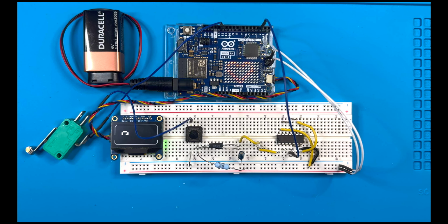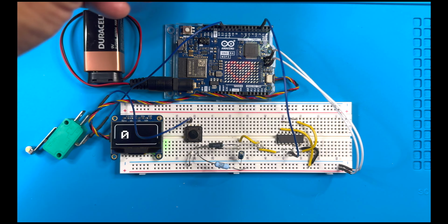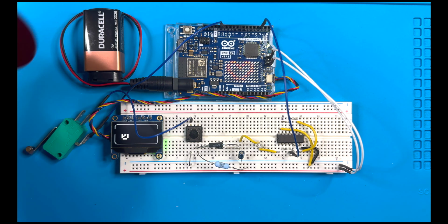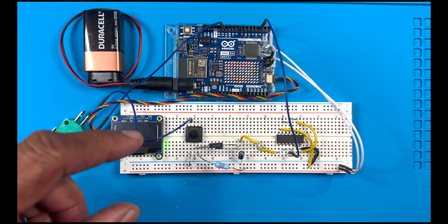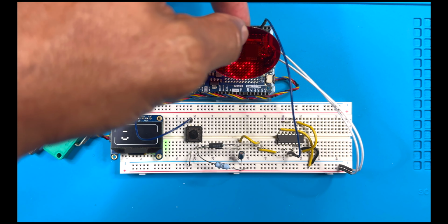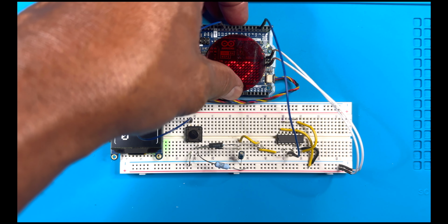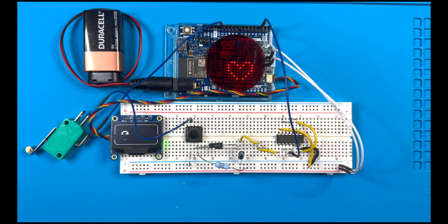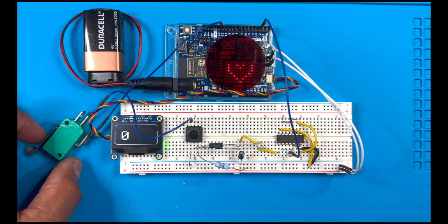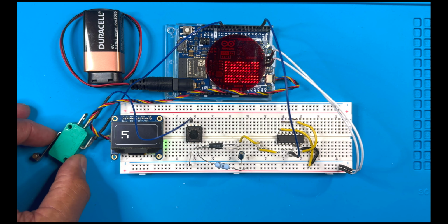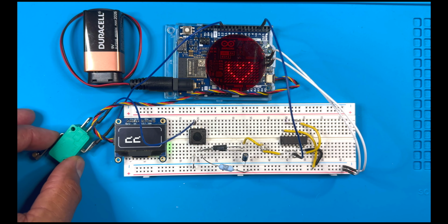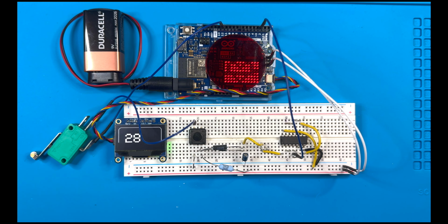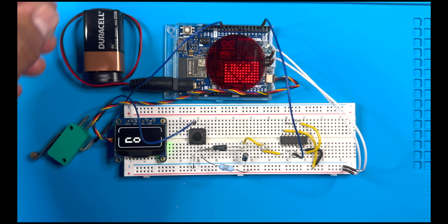Now let's take an operational look at our RC filter network and Schmitt trigger and see how it works. First we're going to look at what happens if you don't have any switch debouncing. I put this filter here just so you can see the heart a little better. We're going to give it 10 cycles. We should get a count of 10. 1, 2, 3, 4, 5, 6, 7, 8, 9, 10. You see that's not the case. A lot of switch bounce there.